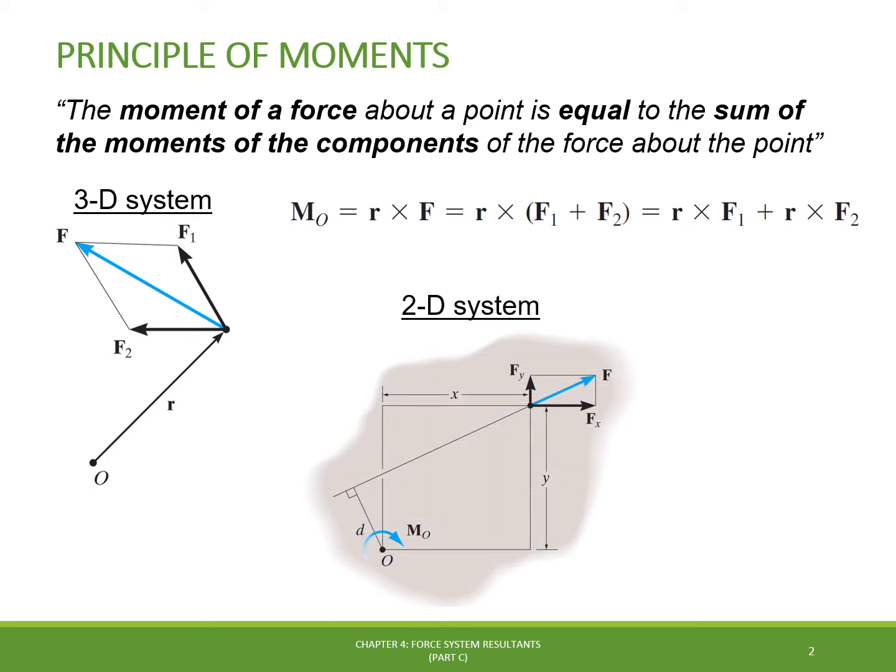For 2D problems, the application of the principle of moments gets even more appealing, since instead of using the moment arm d and the resultant force F to calculate the moment using this equation, we take the rectangular components of the force Fx and Fy and the coordinates of the point of application of the force x and y and use this scalar equation to calculate the moment.